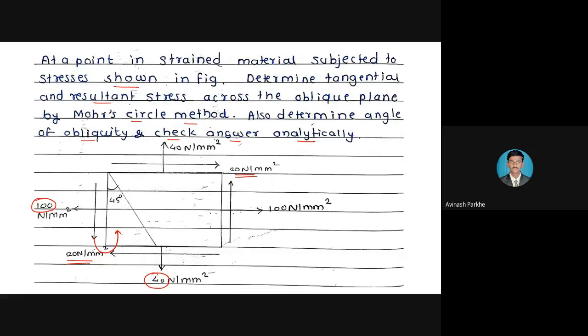And if the shear stress rotates in clockwise direction with the minor principal plane, or horizontal plane, then that shear stress we have to represent in the positive region.